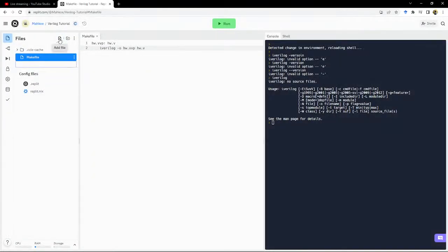And let's make a new Verilog file. I'll call it hw.v. Now, Verilog has a lot of very strange idiosyncrasies to it, so just take this first hello world thing on faith. You need to make this module, which we'll call, I guess I'll call it top, end module. And we're going to do initial, begin and end, and $display "hello Icarus".